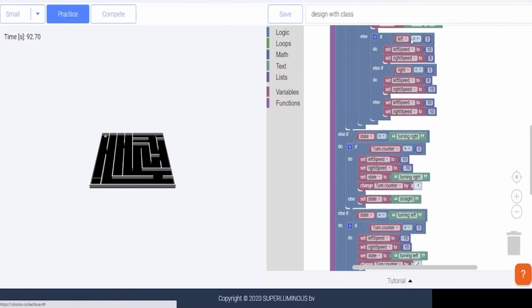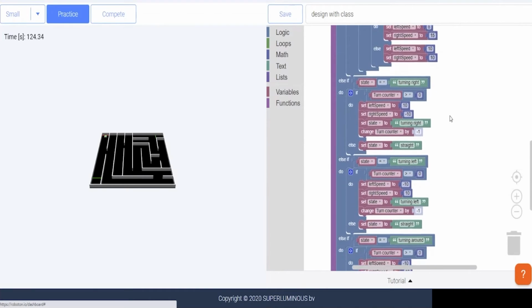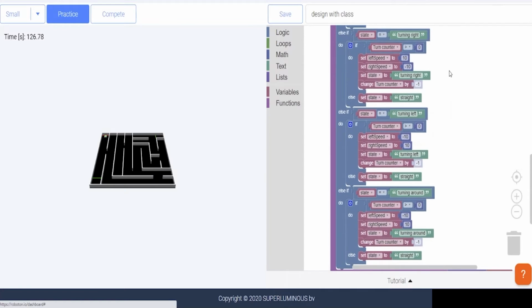Here we've got our little bit of code that says if the wall to my left is too close, closer than 5, I've maybe veered too far to the left, so I'm going to increase my left speed and centralize myself. Otherwise, controversially, if the right side is too short, we're going to increase our right motor and steer ourselves back into the center of the path. If both of these criteria aren't true and we've got no sensors, we're just going to go straight. Okay? That's basically all of the sensor checks. I think you mean conversely, not controversially. Yeah, but just the opposite of that.